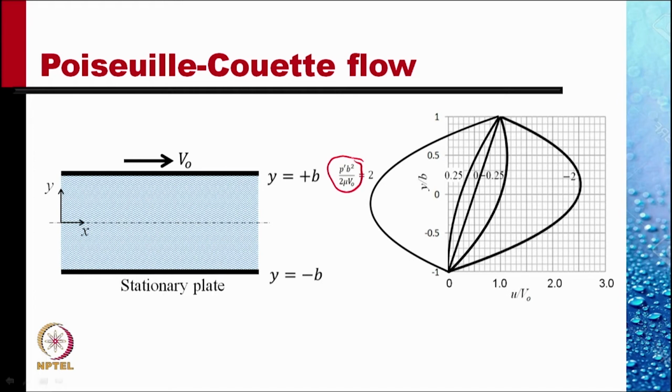Non-dimensional numbers. When there was no pressure gradient along the tube, the profile was a straight line. For negative pressure gradients, the velocity profiles are like this and this. For positive pressure gradient, that is, the pressure increasing downstream, the velocity profiles are pushed back, this and this.